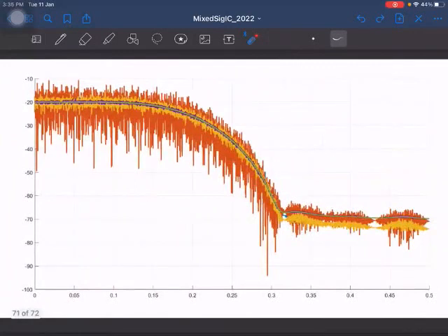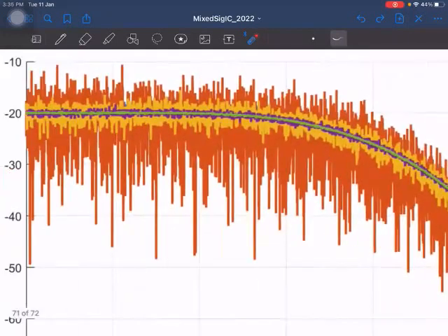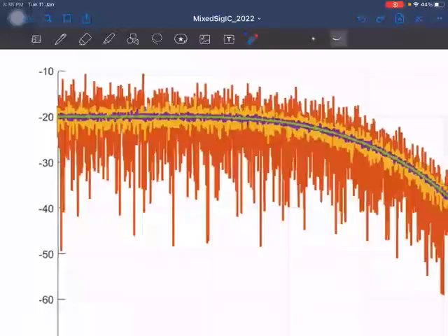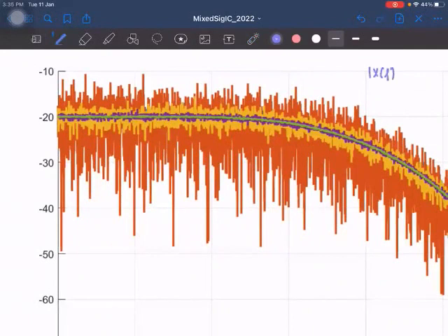So this is another case where instead of taking a white noise, which has a constant power spectral density, I've taken a noise sequence which has a frequency shaping. If I zoom in, we can see the portion in light green, the curve I'm drawing on top, is the actual power spectral density of the signal. And the red one here is the mod square Fourier transform estimate for one segment.